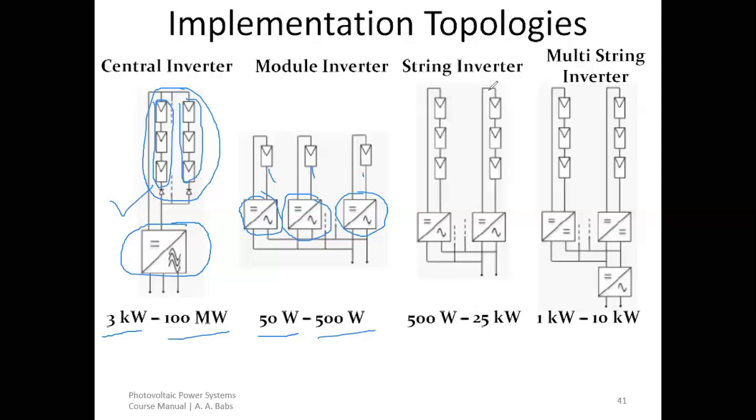So that means if we have 1,600 modules, we are going to have 1,600 divided by 80 inverters, all right? So 1,600 divided by 80 would mean 20. That simply means that particular PV farm would have 20 inverters if we have 1,600 modules installed there. And each string is made up of 80 modules connected to one inverter. So with 20 inverters, each inverter connected to a string of 80 modules, we would have our PV farm properly connected to the available inverters that we have.